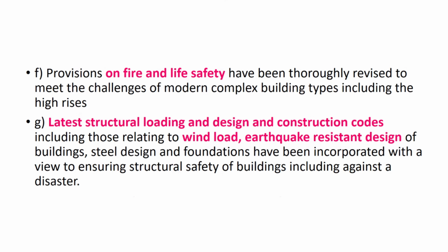Now as you can see, suppose the plinth beam or any beam which has been provided. Now these people, those who are related to sewage related activities, they are making some plumbing connections, and they are again cutting the entire plinth beam itself for making some provisions for their own location as well. Here you can see he has cut the entire beam, put the entire pipe through that, and just made some type of water onto the top of it.